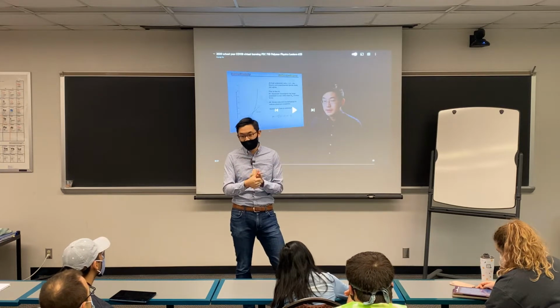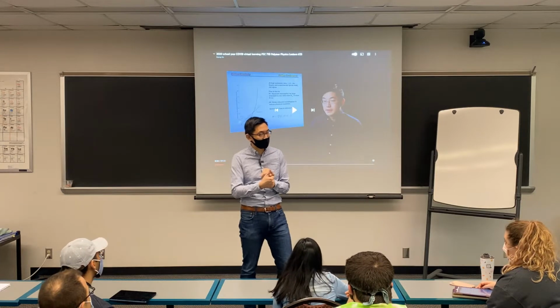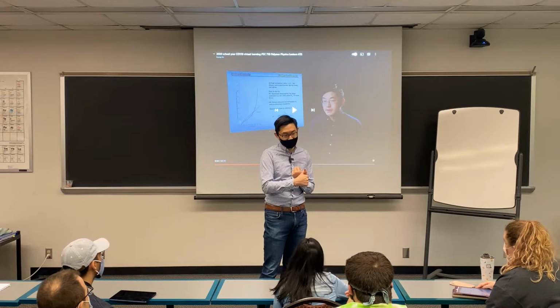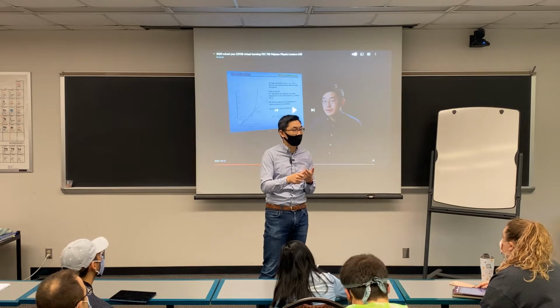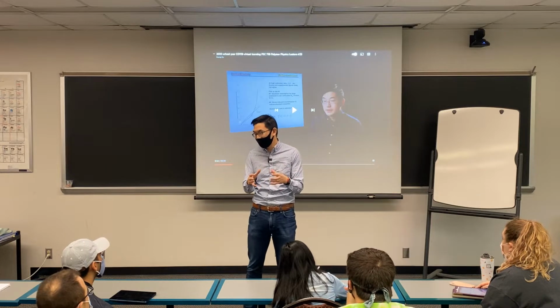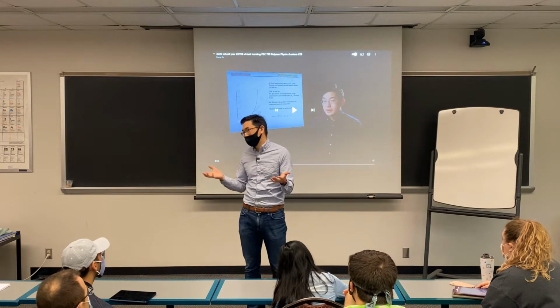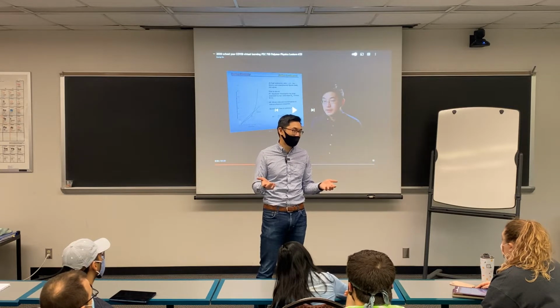So temperature plays a big role in crystallization. You can see when the water is below 0 degrees Celsius, it crystallizes. And once crystallized, it changes many properties, modulus, and many others. So when the polymer crystallizes, the crystal regions are higher in density, as well as higher in mechanical response.